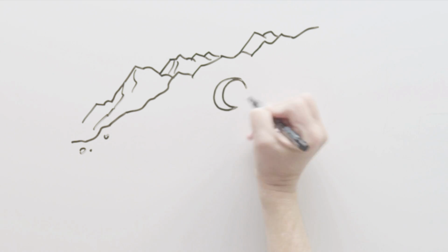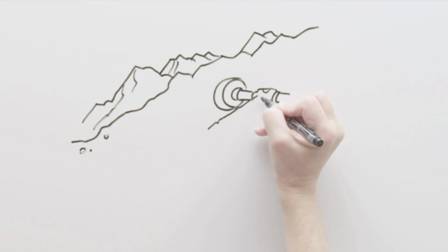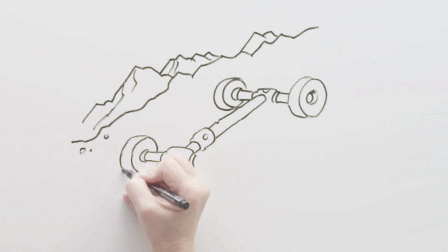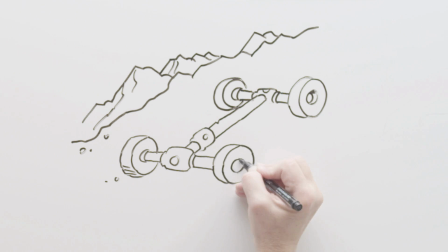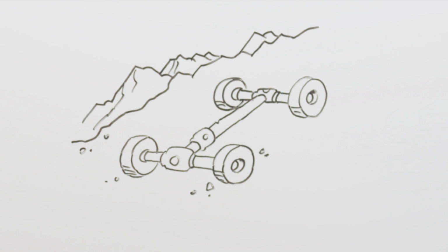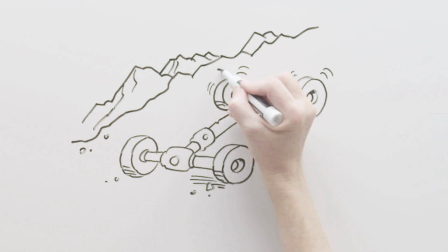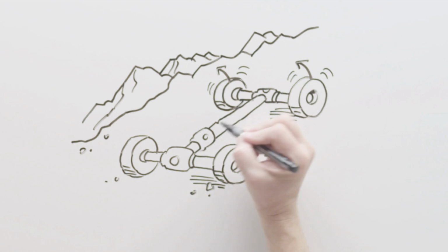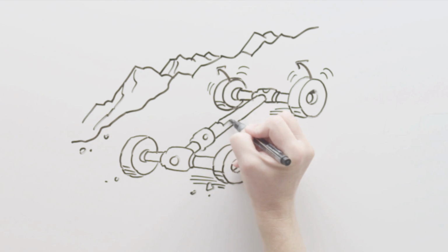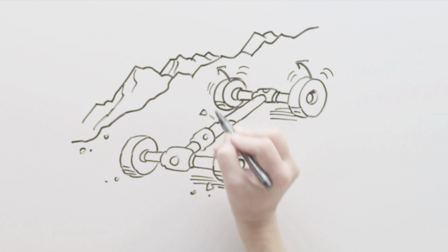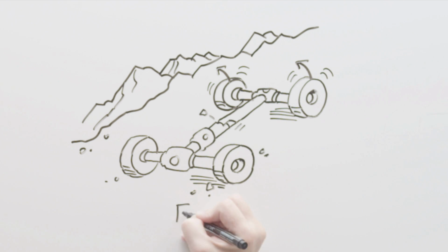They are design verification tools specifically built for the FANG challenge that use physics-based simulation to predict system performance based on component attributes and interactions. Test benches also recognize when the operational limits of any of your system's components are exceeded. For example, if an incline test bench analysis finds that the torque limit of your drive shaft is exceeded during an uphill climb, your design score will reflect a failed design.